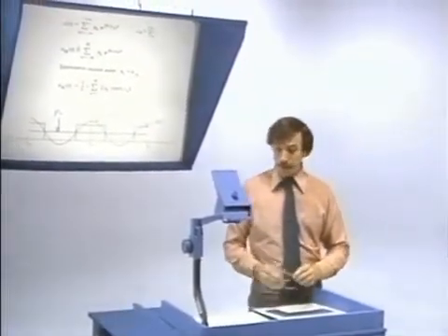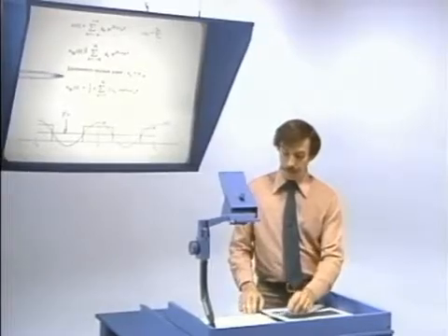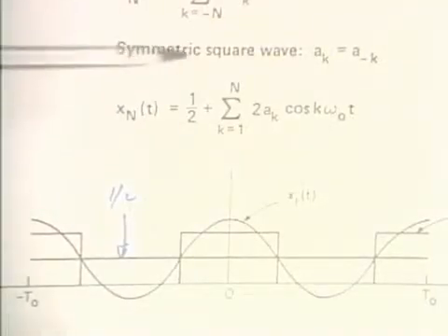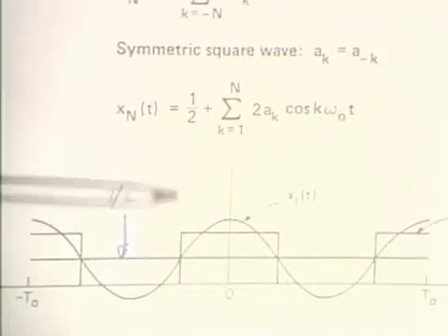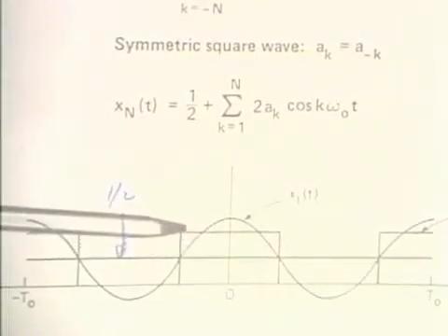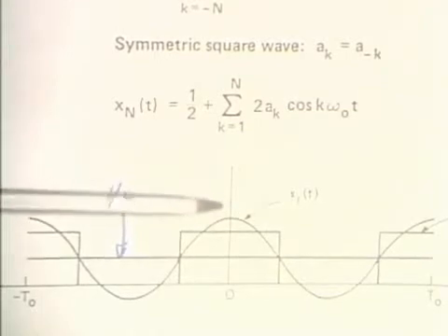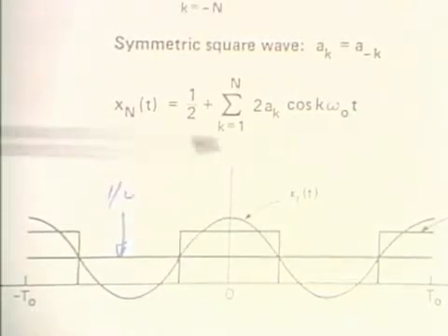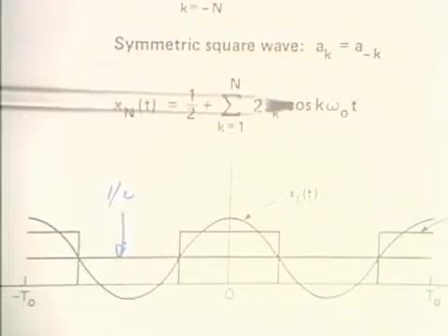So going back to the square wave, it satisfies either one of those conditions, and so the consequence is that with the square wave, if we looked at the error, then in fact what we would find is that the energy in the error would go to 0 as we add more and more terms in the partial sum.